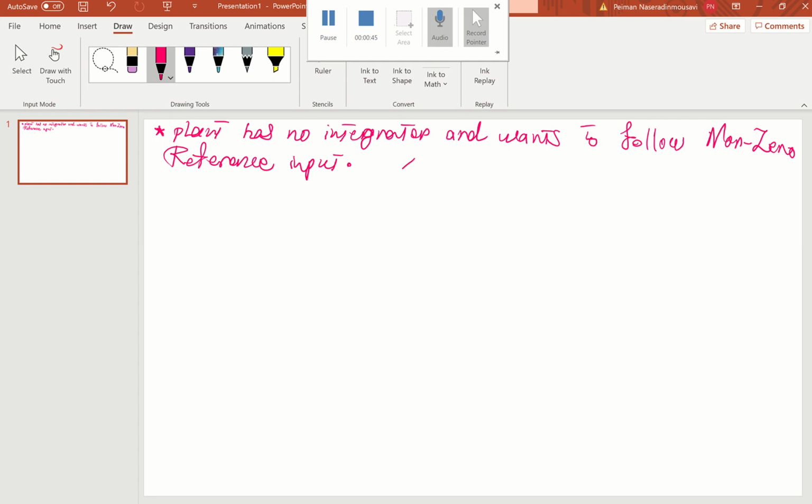So in the previous class we said that this LTI system, that I'm going to extend to the MIMO system by example, is x dot equals Ax plus Bu, and y is equal to Cx. So we added a parameter that adds to the order of the system by 1, which is r minus y, which is r minus Cx, that's right.